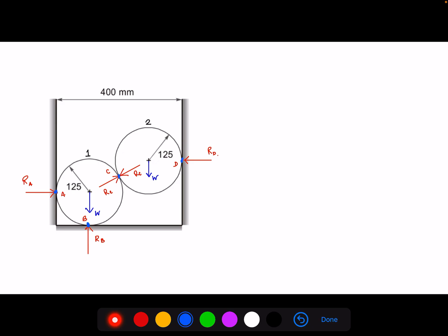But please understand, in this kind of question, when you are drawing the forces, finally to come up with the answer, if there are 3 forces you can apply Lamy's theorem, or you can resolve the forces and come to the answer. In any case, you will require the angle between the forces, and that is why the dimensions are given. So let us see how to find out the angle.